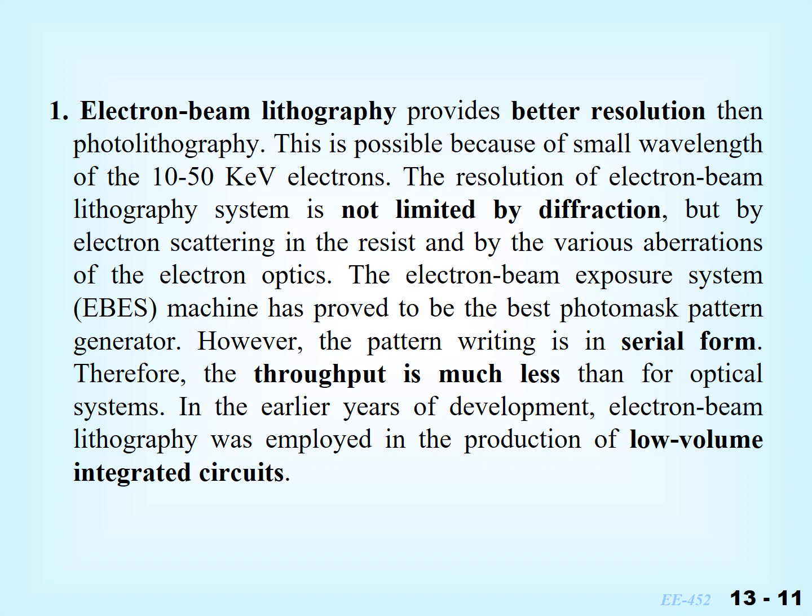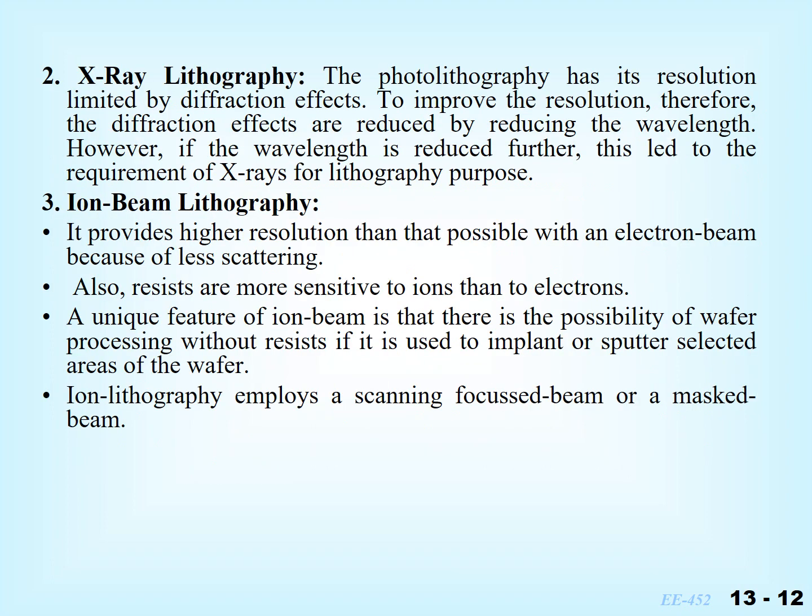But the process has a low throughput. That means the total number of ICs that can be manufactured using e-beam lithography is less as compared to photolithography. Another technique for fine line lithography is X-ray lithography. Again, the resolution is better in X-ray, because it doesn't have diffraction effects.